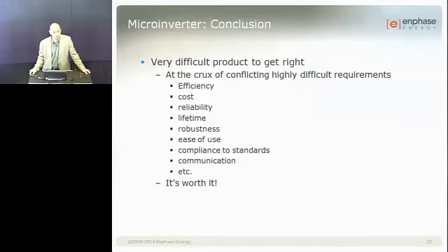And we find that sometimes you change some very small things, and all of a sudden things start going bad. We had a problem not long ago. It was just a resistor, and the value was changing over time, and if you bake it at 85C for a while, it will go back. But there are some bizarre problems you never expect to see on a stupid resistor. So you have to chase them all.